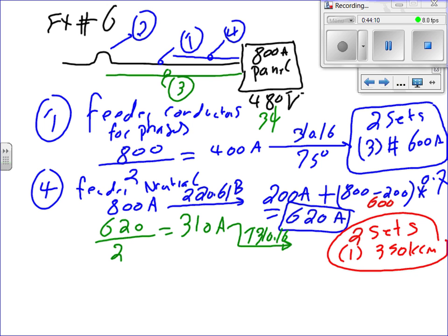Okay? Look at the phases. What was the phases? 600. The neutral, 350. Did we do something wrong? Where do you get 620 from? Because you can't derate the first 200. Yes. So then you have 600 left over, you're taking times 70%. Yeah. 420. It's 420, isn't it? Plus 200. Oh, you're adding, that's right. Yeah, you add it back again. Okay. Is this right here?